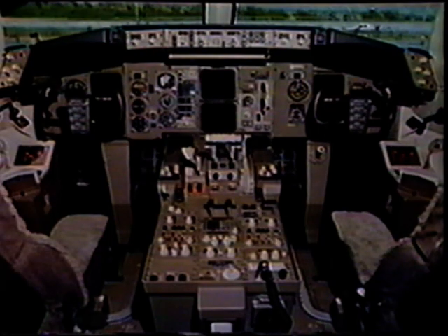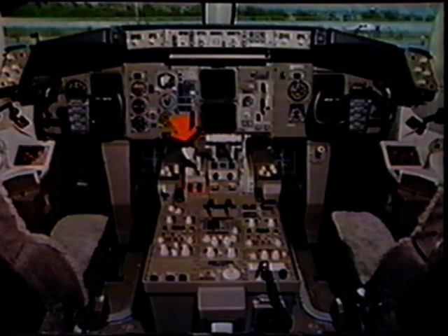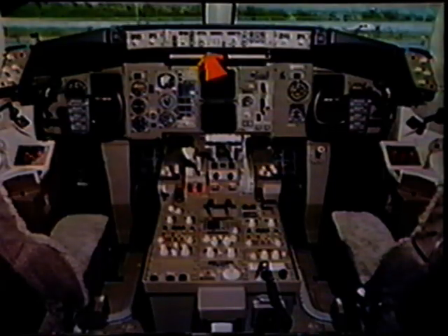A movable, single-span horizontal stabilizer extends through the aft section of the fuselage and provides a means of trim in the pitch axis. The horizontal stabilizer is controlled by manually operated electric trim switches on each control wheel and manually operated levers on the left side of the control stand. Automatic operation of the stabilizer trim system is controlled by the autopilot control system.